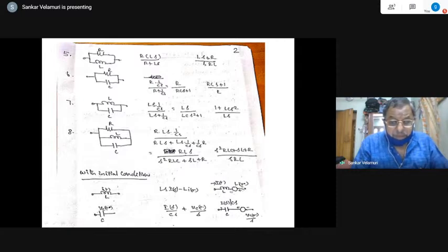That is why, when the supply is switched on, the initial current flowing through this is I0 minus, and it can go to the other part of the circuit, if at all that is considered. So the polarity of this in the branch will be I S into L S, and suppose I S need not be considered, then the short circuit current will be flowing through. Then L into I0 minus is going to be the corresponding voltage obtained, making this a short circuit. Right. So this is the equivalent circuit concept using the transform network parameters.